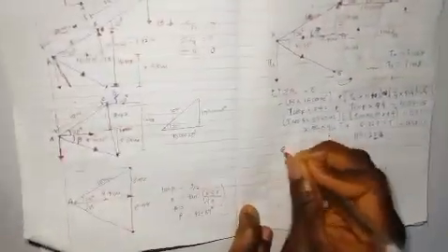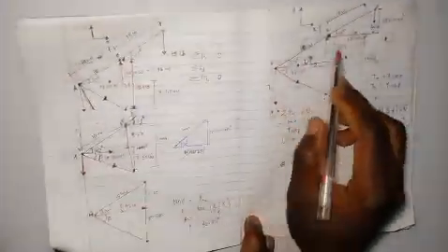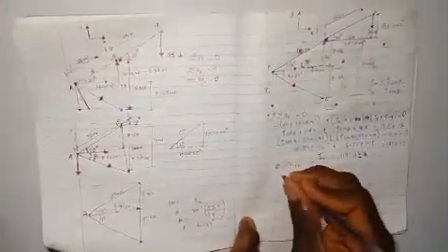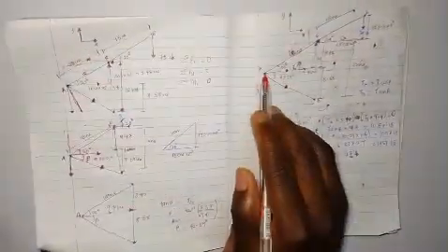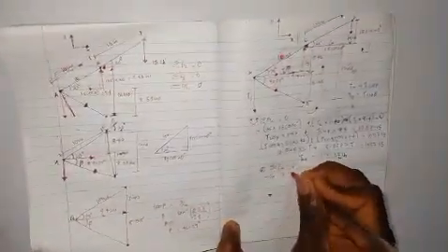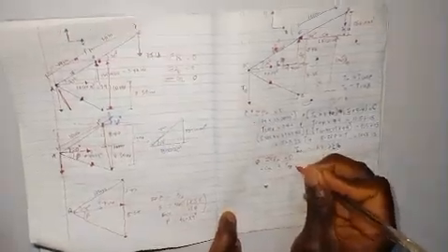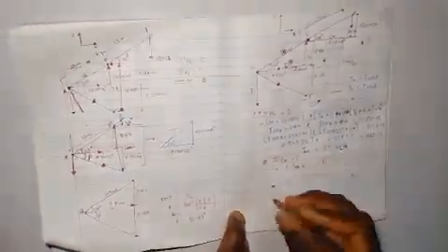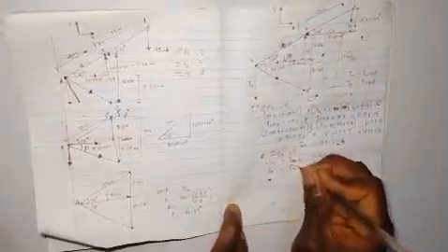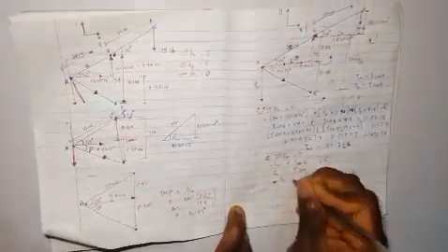Now the next thing that we are meant to do is, let's take the summation of Fx to be equals 0. Now the first one we are having our Cx. Don't forget, going towards the negative of x, so that's minus Cx. Then the next one we are having our Tx, T_AD of x, going towards the positive, plus T_AD of x is equals to 0. So that means our Cx will now be equals to the tension which is of x, which is T cos beta.